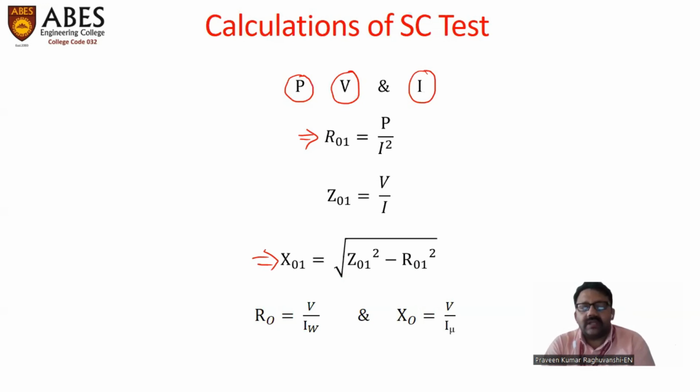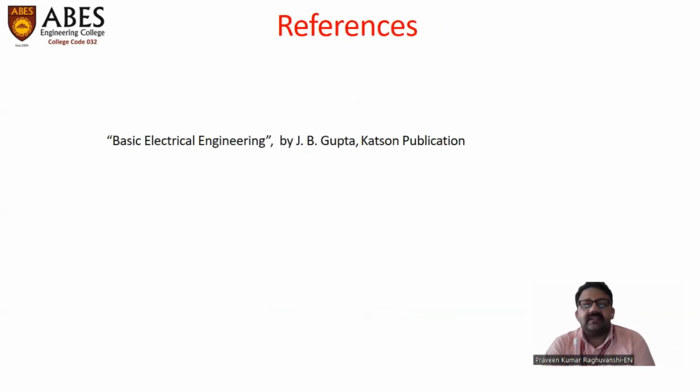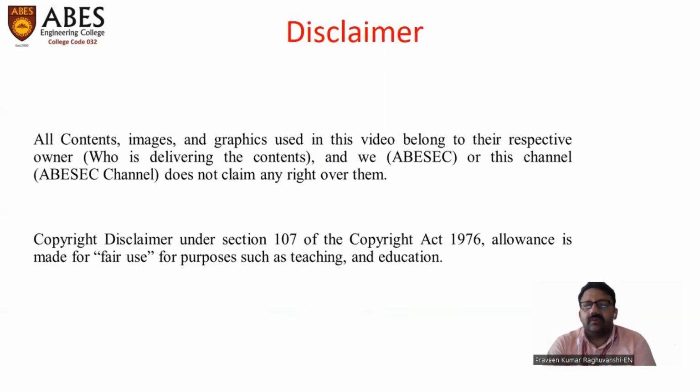So this is how we conduct the short circuit test. This is the reference used for making this video. So this is how we can perform the short circuit test on a transformer and determine its copper losses.